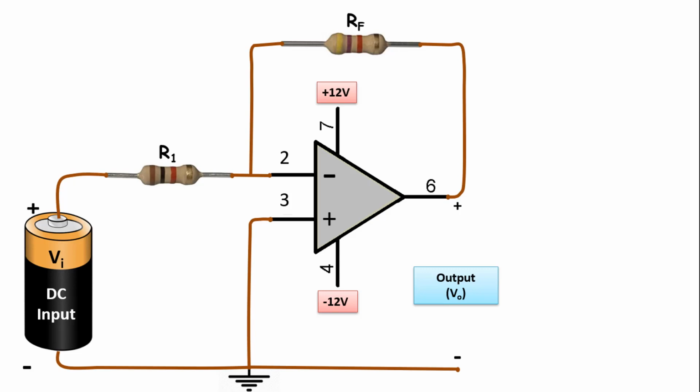So, how do we find the output value? If we show the input value Vi and the output value with VO, VO equals negative Vi times RF over R1. If you ask where we found this, a Kirchhoff voltage law is written at the input, and a Kirchhoff voltage law is written between the input and output. Since the currents are equal to each other in these two equations, this equation comes when you replace each other. If you wish, you can look at how it was found later from another source.